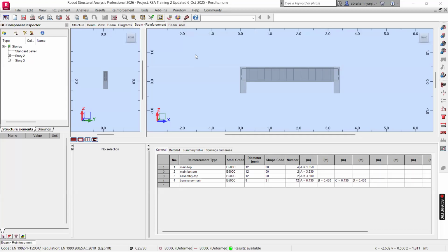So if you design that specific slab to carry the load of your tank when it was full, say 20 kilonewtons per meter squared, and the slab can withstand that, then it will withstand carrying an empty tank that is only accommodating self-weight. So if your slab passes for the worst case scenario, then it will stand if the tank is halfway or empty.